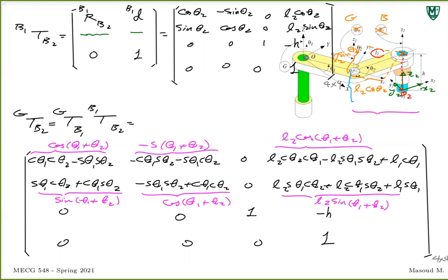What I want you to be able to do is find the transformation matrix between 2 frames. That's the important step that no software can do for you. If you do that, the mathematics of it, you can use any software. You can just multiply this and simplify that and get the transformation matrix, as long as your transformation matrices between frames are correct.